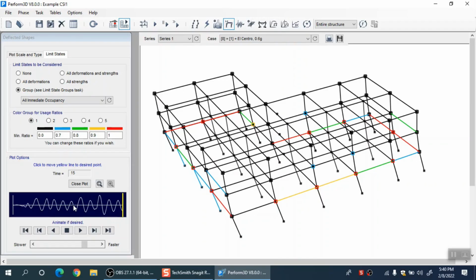For beams, a beam is a local element. Its purpose is to just transfer the area load to the columns and other supporting elements. A column is a critical element, right. So, if a column is yielding, for example, in flexure under an earthquake level in which it is not supposed to yield, then obviously it requires a design decision.